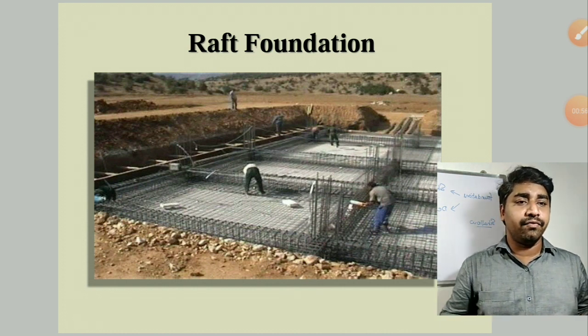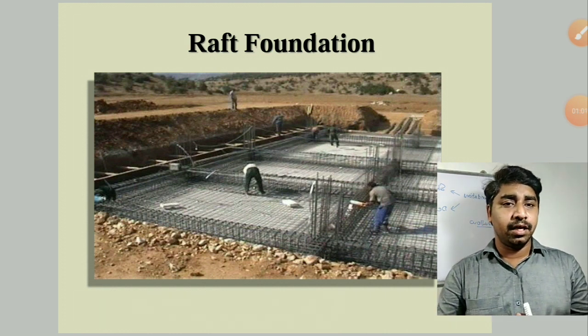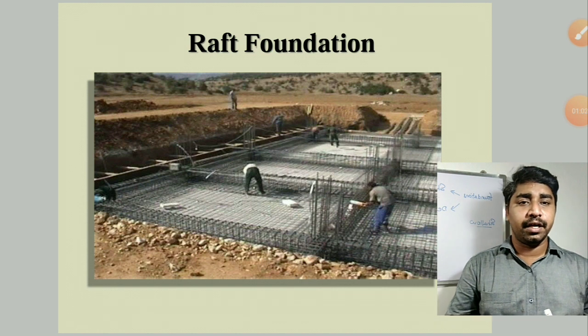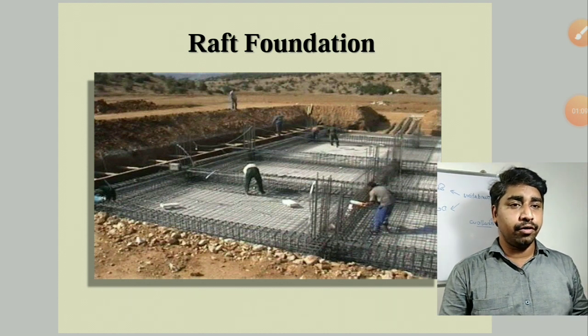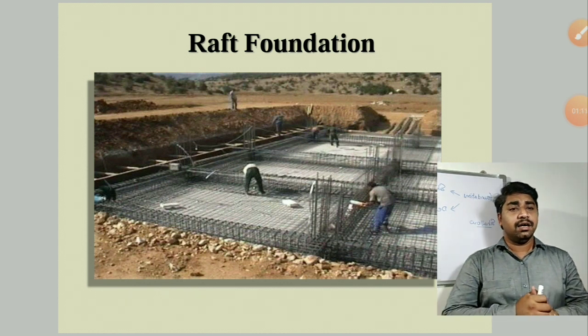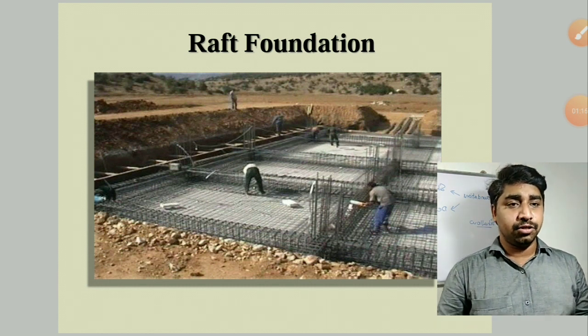The entire foundation or the entire floor area is going to be provided with foundation with reinforcement and concrete. We are going to provide a mat foundation which is going to distribute the load evenly in the cases of highly compressible soils and in the case of highly susceptible soils.